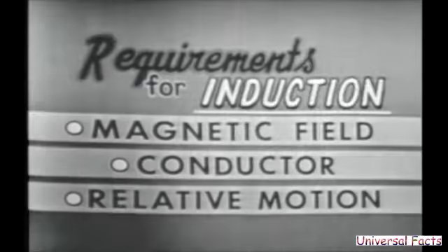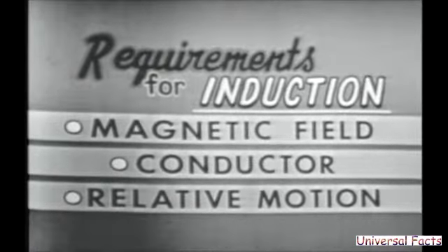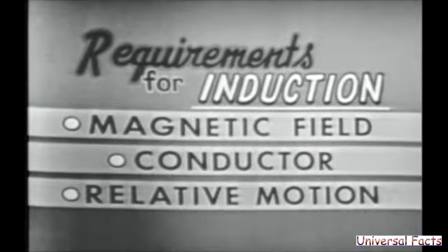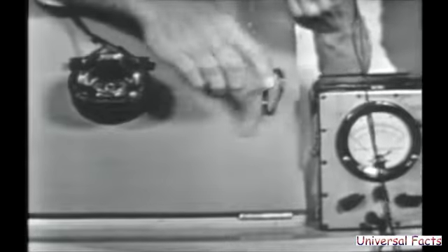Well, you remember the requirements for induction? I sure do. A magnetic field, conductor, and relative motion. All right. We've got a magnetic field here that's rotating about the field windings. I'm going to take the rotor out of there and prove that we have induction taking place.